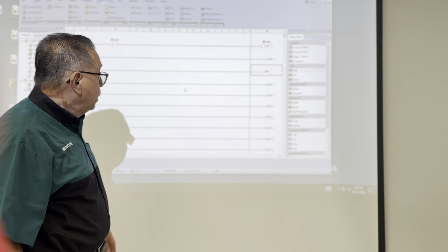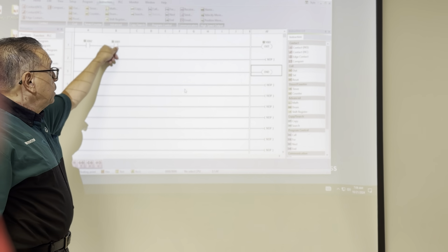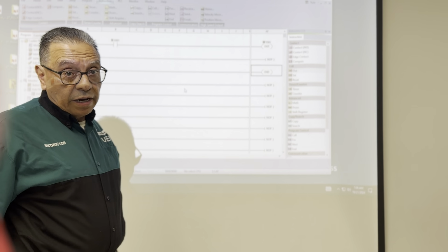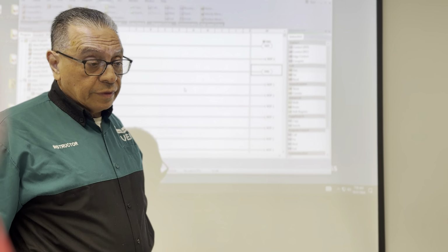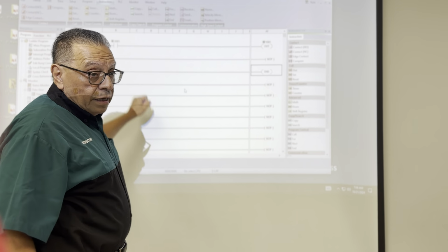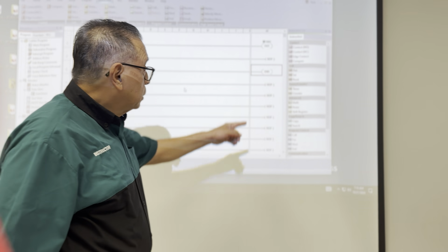For example, if I have a thermostat connected in series with a motion sensor, and I preset my ambient temperature at 78 degrees Fahrenheit, both of them should be closed in order to have an output.